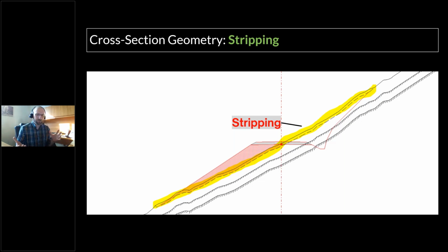So it's going to change the volumes that we're tracking. The stripping layer, you don't want to build with that. You don't want to just pull that off and incorporate it in your fill and have some poor material mixed in with the stuff that you've taken the time to shape into a road. So that's going to be tracked as its own entity. And since we are taking, in this case, a foot off our road, we're effectively dropping down the topo surface. So we'll want to drop down our grade so we can balance that as it was before.